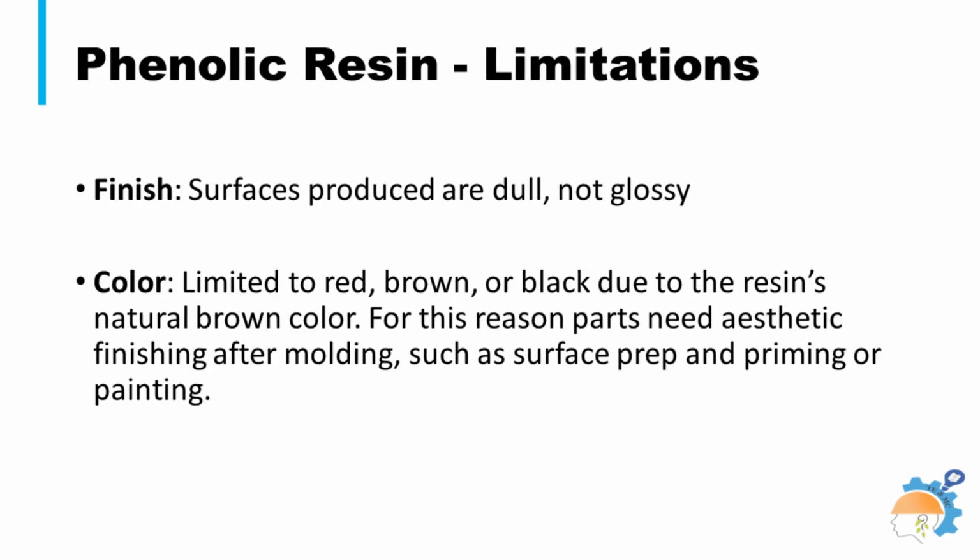Phenolic resins are prone to cracking under impact, often needing fillers for toughness. Phenolics produce a dull finish. Unreacted phenol and formaldehyde are hazardous and require careful handling to reduce emissions. Phenolic composites are heavier than some materials and have higher initial cost than basic alternatives. These undergo significant shrinkage during curing.